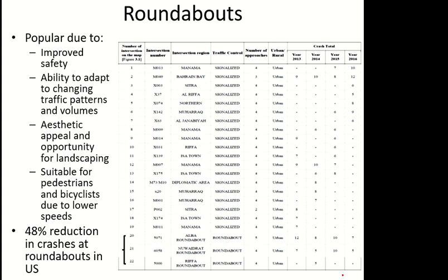Then at the roundabout, vehicles enter and leave as they are turning. So when you enter the roundabout, you are turning into the roundabout, and when you leave, again you are turning out of the roundabout. So at turning, your movements decrease. There is no straight going in and out, right? You are always turning, so your speed is always lower. Even if there is no conflicting movement and you are the only driver entering the roundabout, you will not do it at fast speed because you have to go on a curve. So speed is lower, and lower speed makes it safer for the pedestrians to cross.